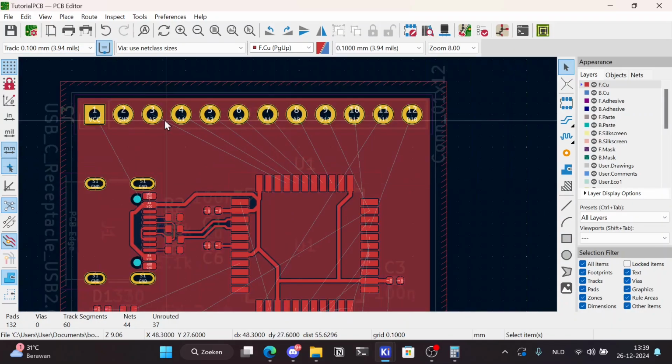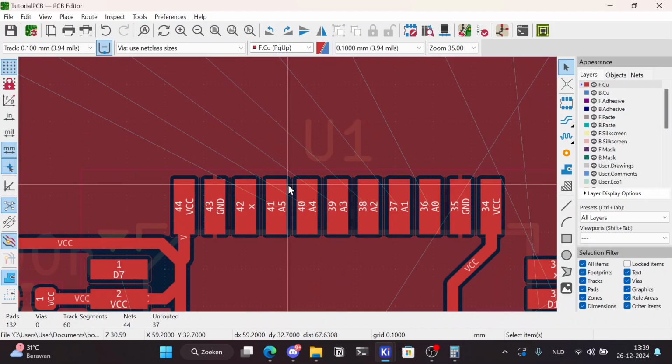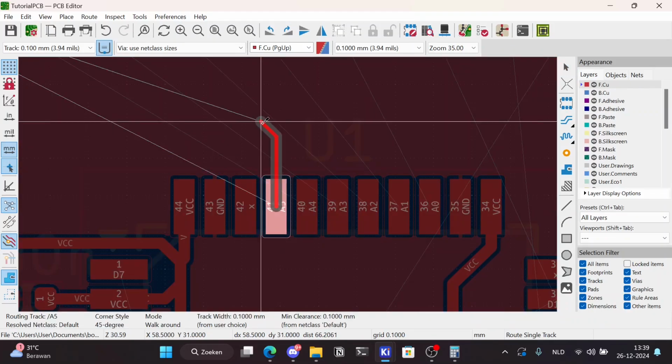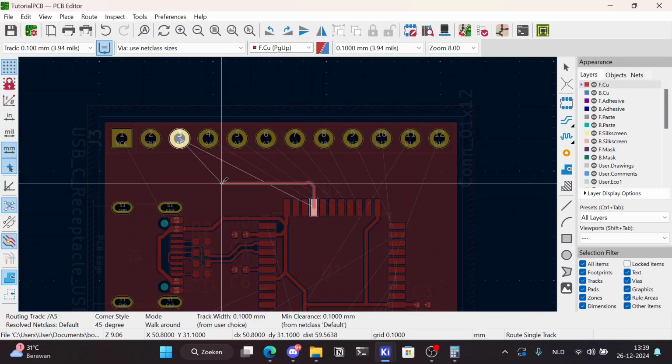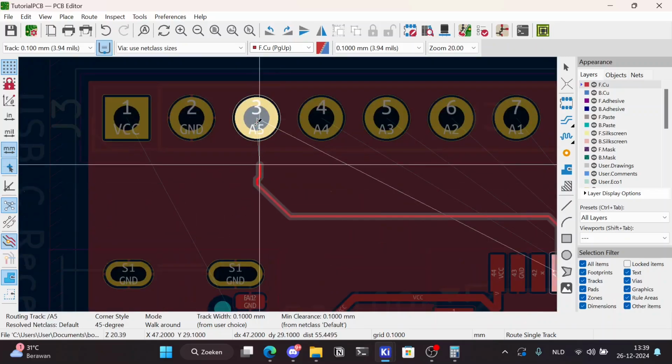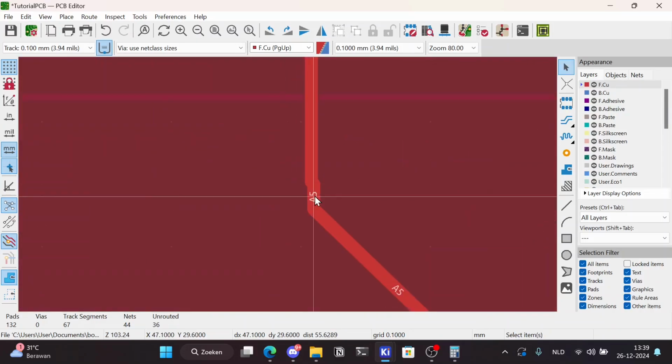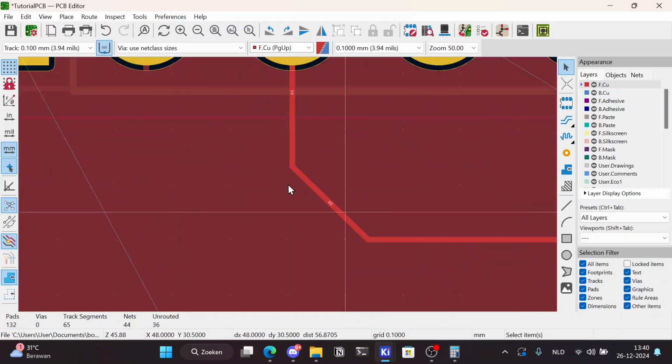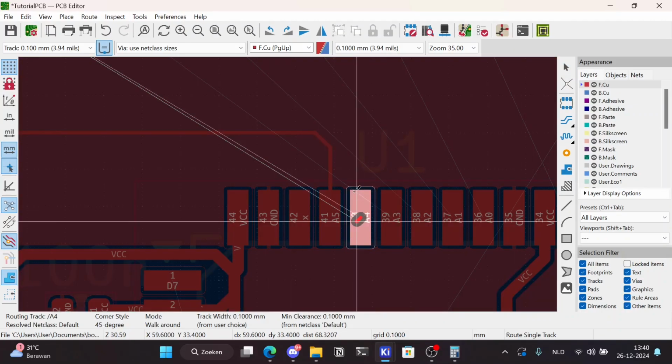As you can see here, A5, A4 all line up with the same pinouts. So you can start routing. I'll do A5 first, and then with A5, if you think this track wiggle is bad for you, then you can just correct it out. Here we'll use A4,